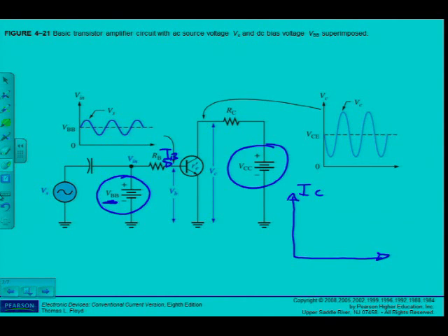remember we talked about the characteristic curve of a transistor, IC against VCE. And then we've plotted the transistor. We will discuss that again just now. The transistor being used as a switch at cutoff and saturation. Connected 2 lines, that's called my load line, and I know that I will use my transistor as an amplifier in this region, which is called the active region or the linear region.